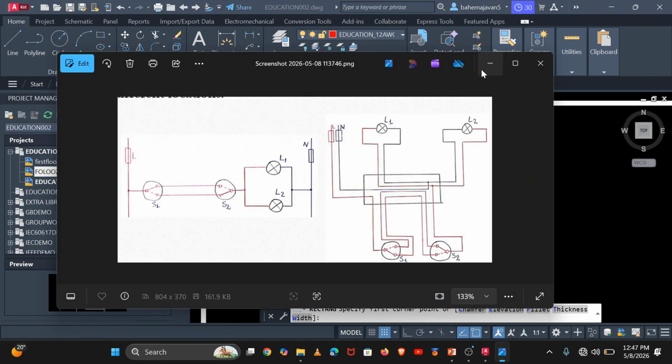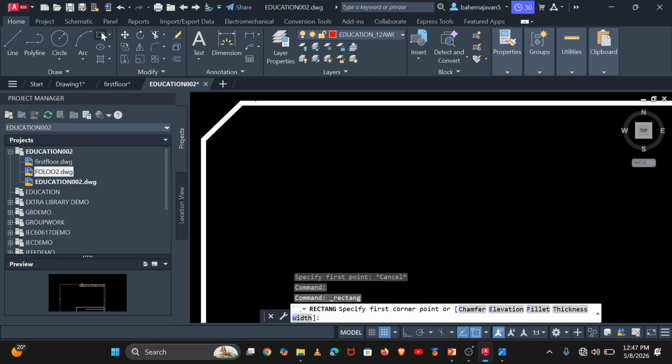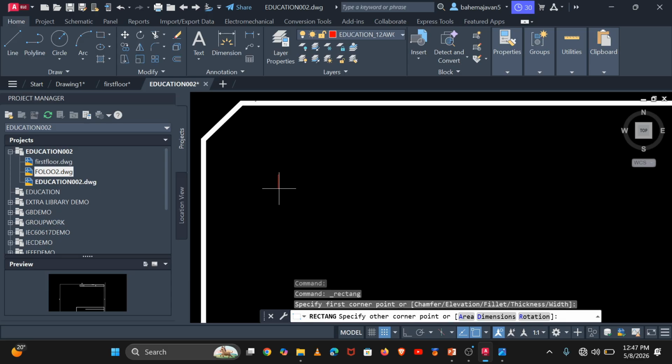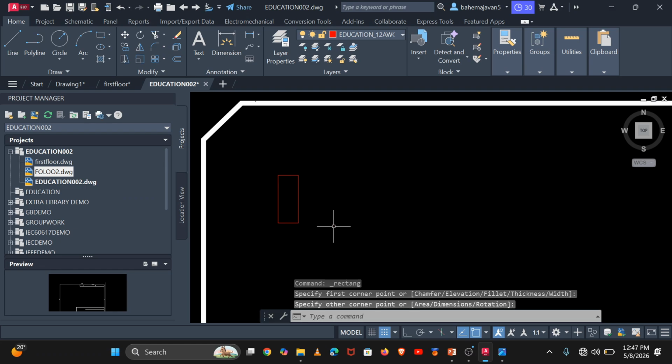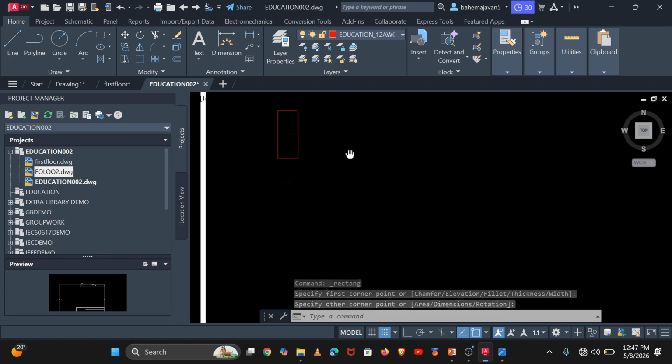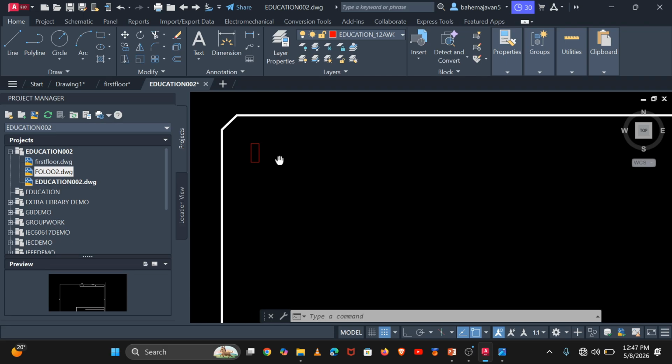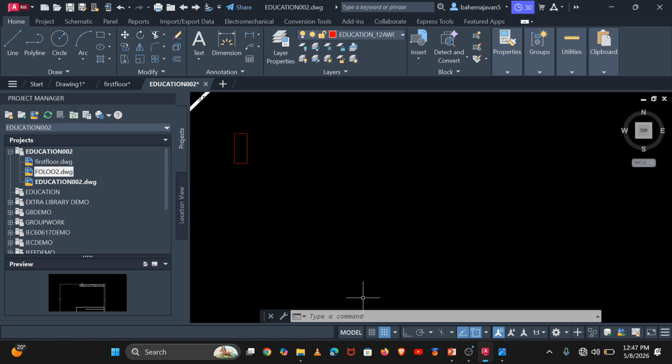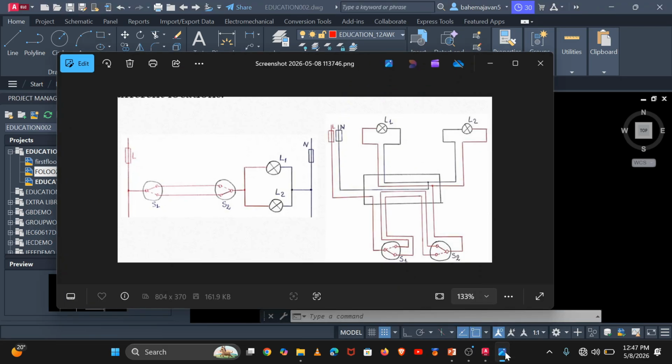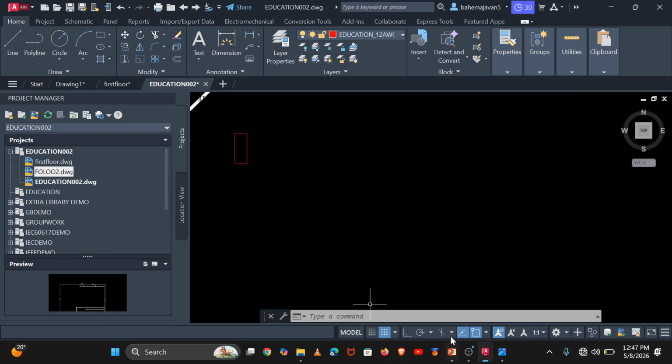This one we will use a vertical drawing like this, and you can see. When you do it like that, you can see how we put there the first, and then a vertical line. We must turn on this orthogonal like this, and then we choose the center like this, because when you hover over this and rise up a little bit, you keep on working on the center line.